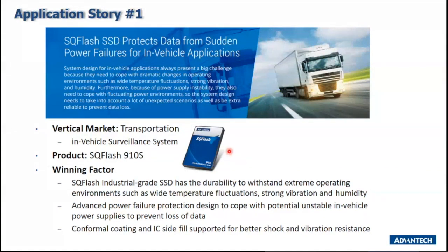SQFlash industrial grade SSD has the durability to withstand extreme operating environments, such as high and low temperatures, very strong vibration, and very high humidity. Besides, we also provide advanced power failure protection to cope with potentially unstable in-vehicle power supplies to prevent loss of data. We also provide customization services like conformal coating and IC side fill for better shock, vibration, corrosion, and water resistance.